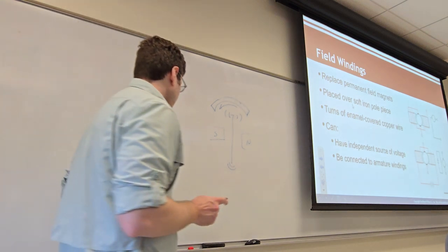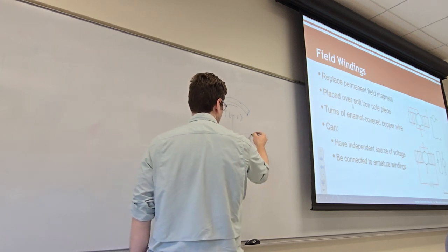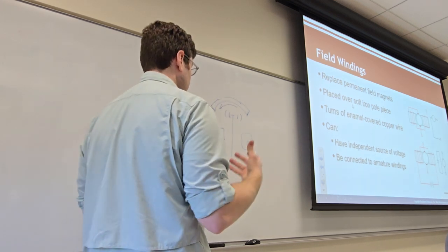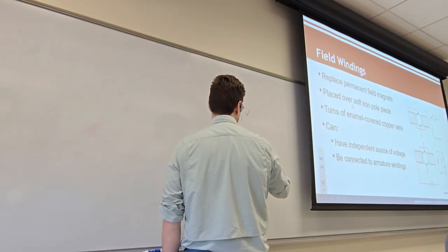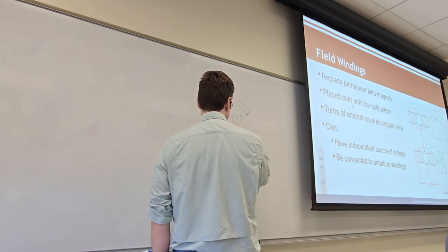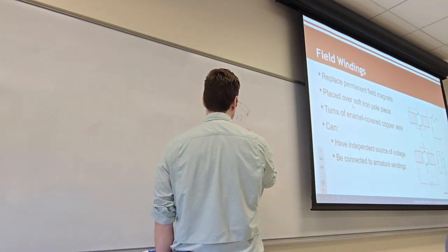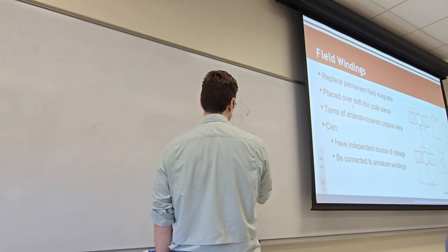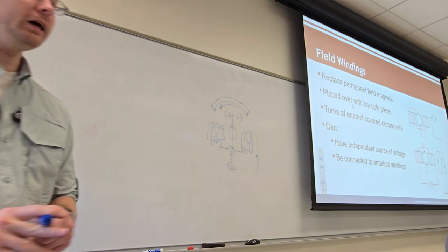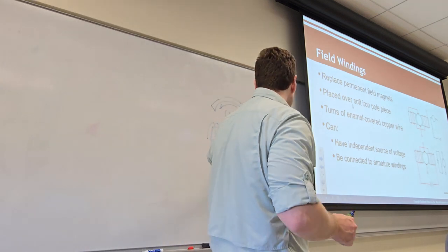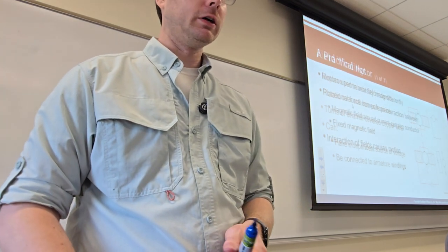So that is for a permanent magnet motor, where the magnet just exists and it has a magnetic field. But what could happen too is that we could also induce or control this magnet. So we not only have our armature that we can control, this wire, but we can control this wire as well. So we have some additional complexity there. That way we can decide to energize the electromagnet here, or we can energize the electromagnet inside of the armature, to get it to kick over.